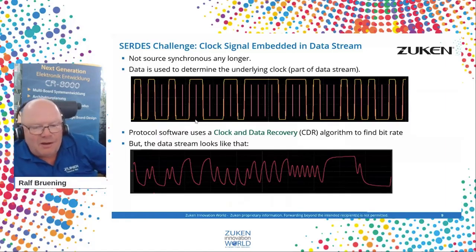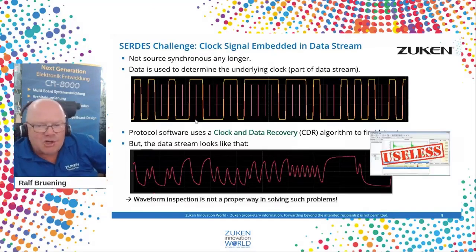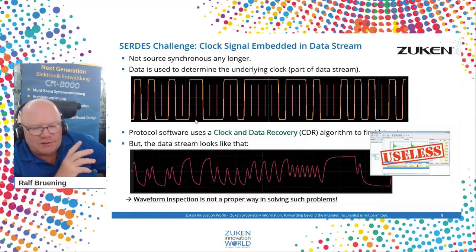So for getting an idea whether this is operational or running into a malfunction, traditional signal integrity analysis, just doing an analysis of voltage versus time of 1, 2, or 5 bits, is useless. That's not a way to address these problems.